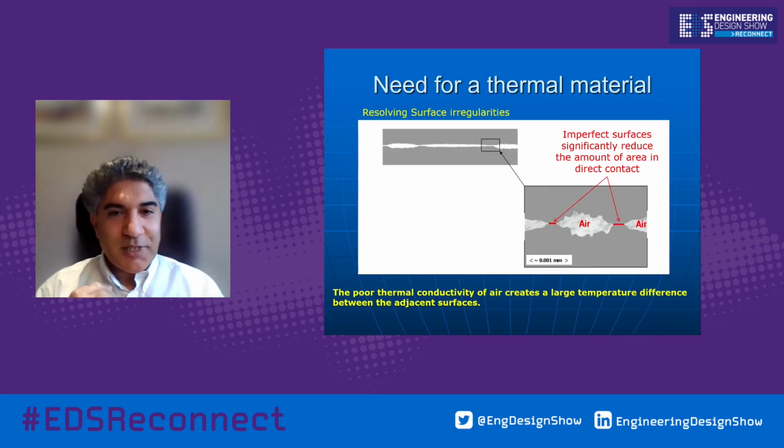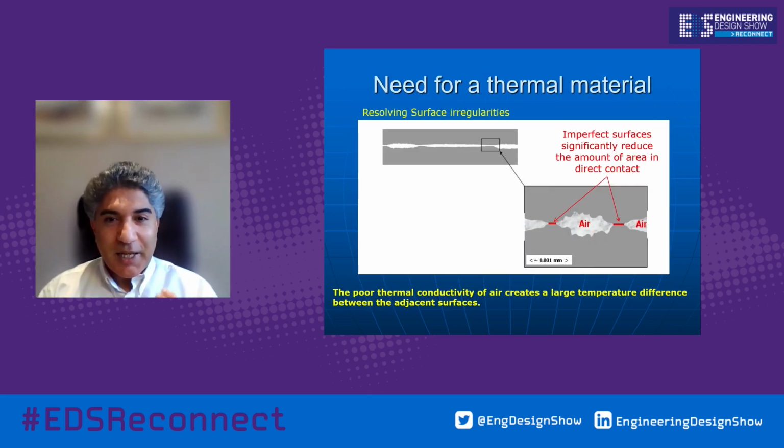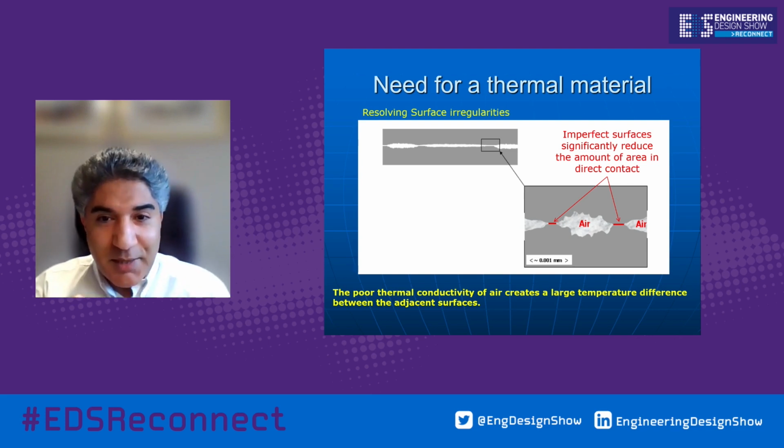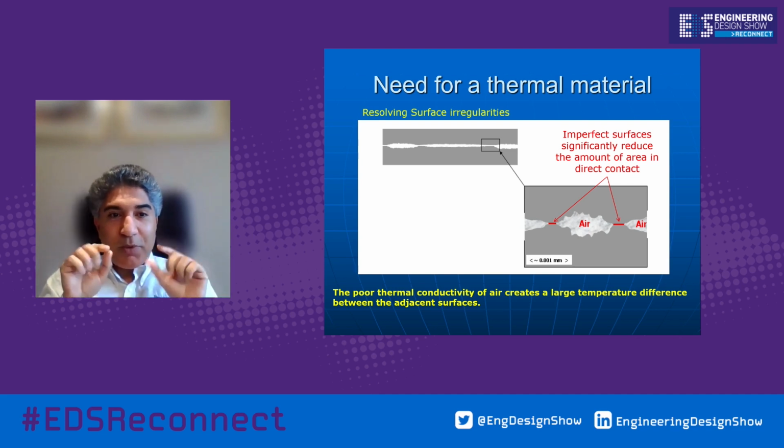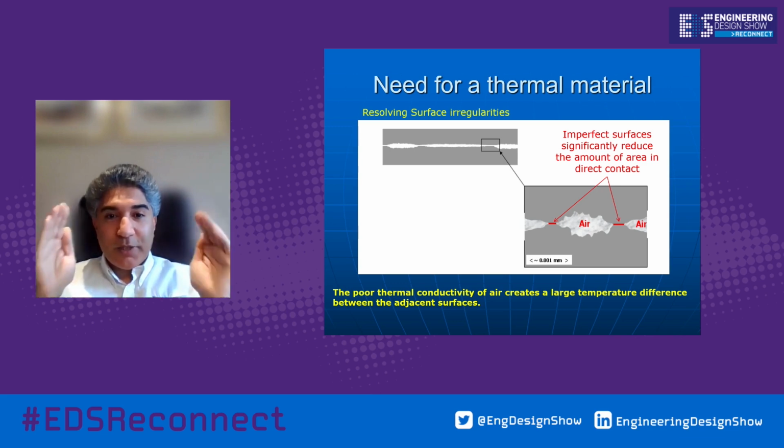Okay. So this might seem over the top in this slide, but these voids or nooks and crannies can compromise or affect your thermal effectiveness to your interface, be it the core wall or a heat sink. It might seem over the top in terms of magnifying from 0.001 millimeter, but what we're trying to do with those nooks and crannies is to fill in those voids with a thermal interface material so that you can have effective heat transfer so that the interface can do its work.